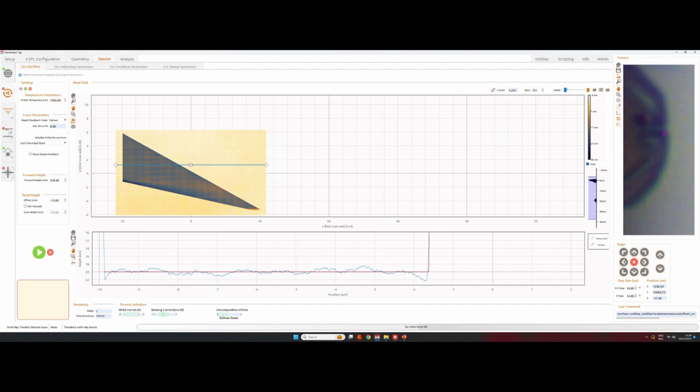Well, the bowing correction is applied based on the result of the reading of the written lines, while the bowing prediction is applied based on the electronic deflection during an out of contact read, in a similar way that is done the thermal conductance correction.